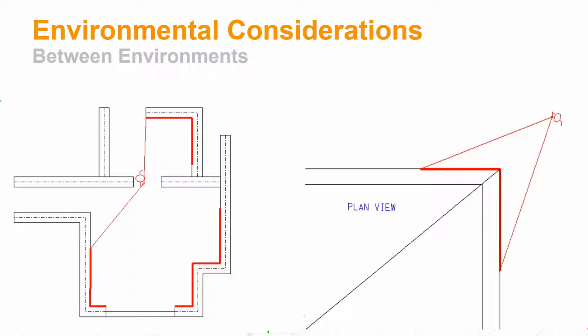If you are capturing with the RT system, it's fairly easy. You can see on the screen what's happening, how good your point cloud is, and if you need to slow it down. Capturing with Horizon, it's much more forgiving with the amount of data it's capturing and the range it has to create the trajectory, but it's still best practice to move slowly from one room to another.